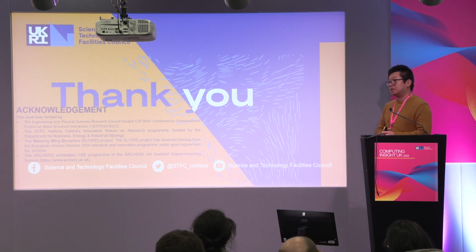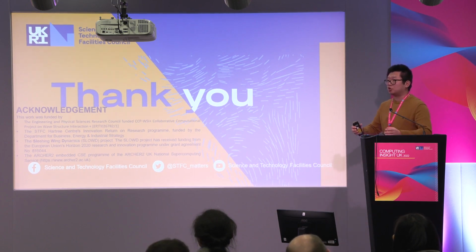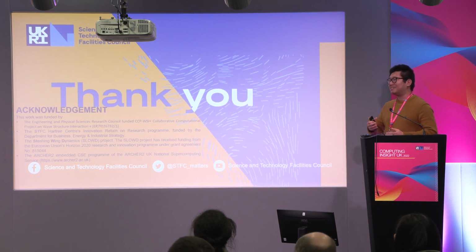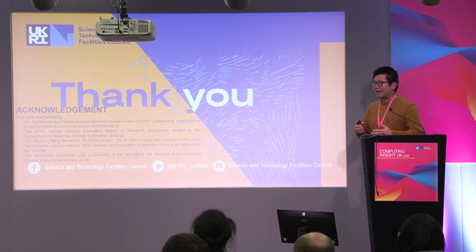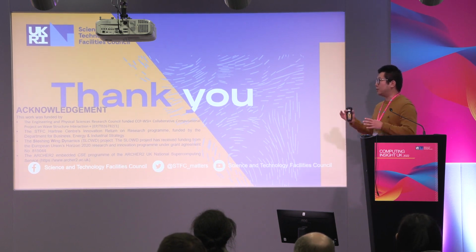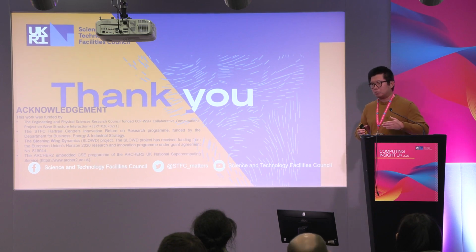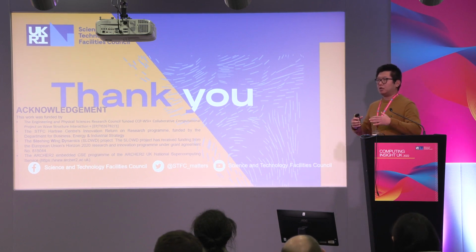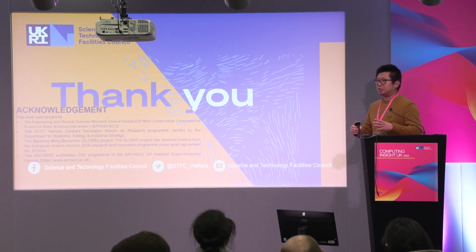Currently, the time marching of the CFD and the CSM are at the same pace, but theoretically we can make it different. As I mentioned in MUI, we have a number of temporal samplers as well. It is a very typical case when we simulate multi-scale cases. Currently, we talk quite a lot about multi-physics, but when we move to multi-scale simulations, different time steps are needed.